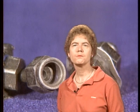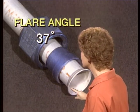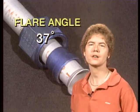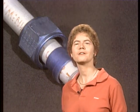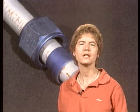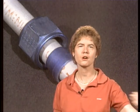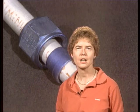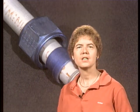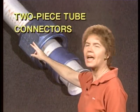If you're flaring aluminum tubing for use with the AN coupling nuts, the angle that you're looking for on that flare is 37 degrees. You're looking for a 37-degree angle, exactly that angle, and that is different than they use for automobile connectors. And it's designed that way specifically to be different than automobiles so that you don't get them mixed up between the two. Don't use automobile connectors when you should be using aircraft ones. Okay, what you use is a two-piece tube connector consisting of a sleeve right here and the nut.